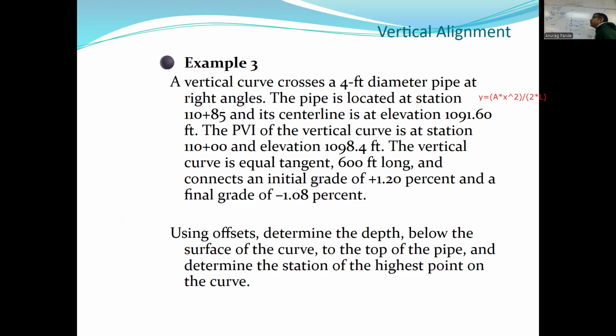Next thing I want to figure out, L value. Is L given in the problem for me? The length of the curve. Do we know L in this problem? We do, right? 600 feet. It's given. I'm going to plug that in, 600 feet. That's good. Now I need to figure out what is the X value for the point of interest.